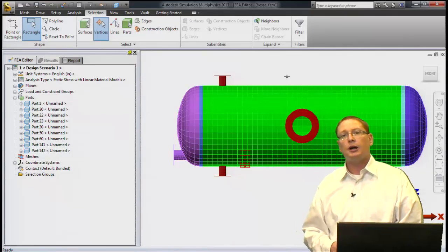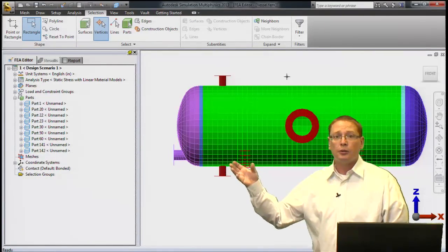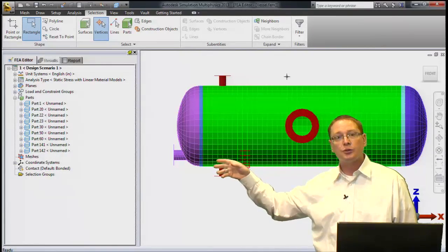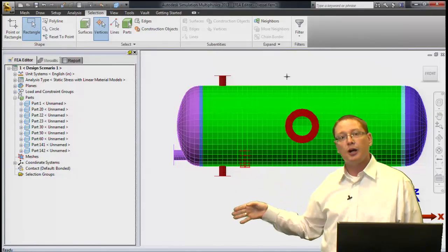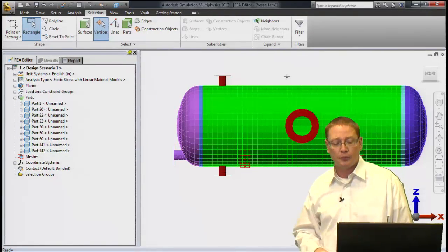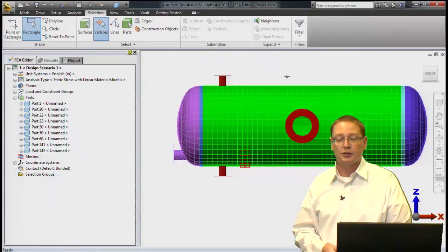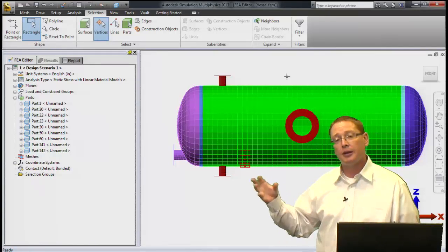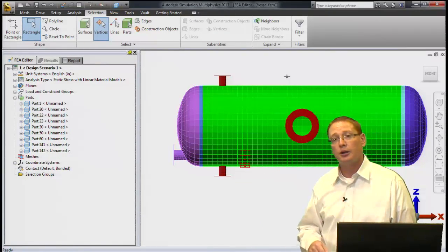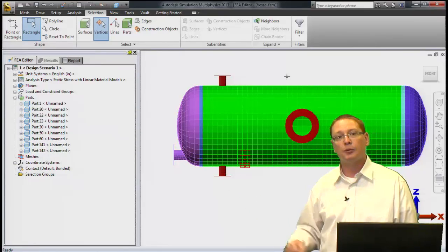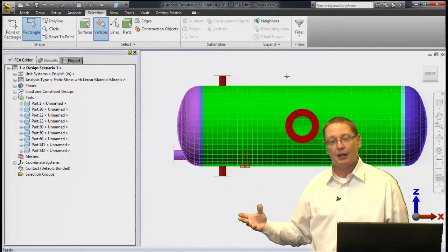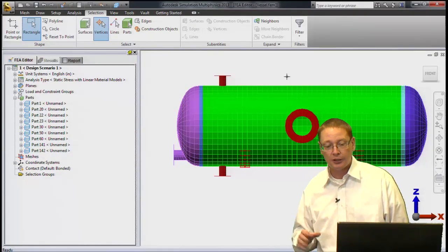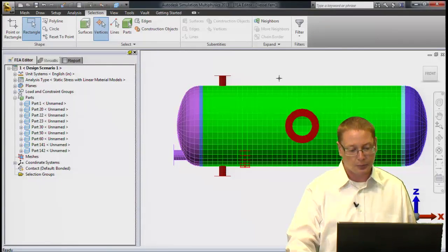Of course, once you're within the FEA editor, before we execute the analysis, what I really have is a series of lines and nodes. So certainly I could take lines here and I could copy them down, extrude them, copy, join them to create something a little more representative of the saddle. I could take these lines here and I could modify them onto another part yet. So I could duplicate them onto a new part number that has not been used yet, and I can assign them a thickness, something representative of the stiffness of the saddle. So there's a lot of different options there. Again, we're trying to keep it relatively simple.